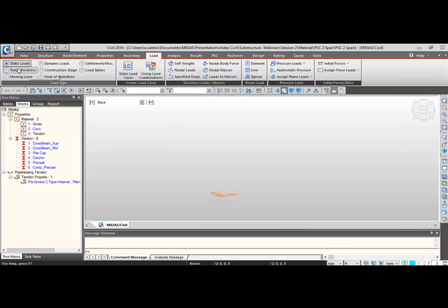You have the load tab. You can define the static load cases, dynamic moving load, etc. And the way the program works is from left to right. So let's say you want to define a load, you define the static load cases, and then you go from left to right. Static load cases, and then here you can define the different loading. So that's more or less how it works in the program.